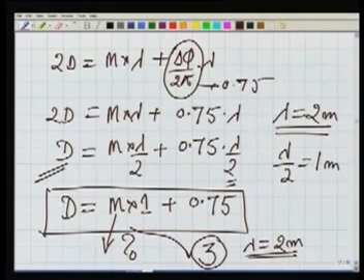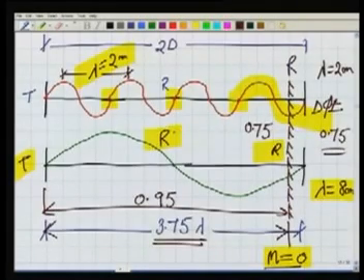Also another thing, because it may be confused that how we are selecting this value of 8 meter, how we are deciding that it should be 8 meter. 8 meter onwards, any wavelength that you select, the phase difference will increase monotonically. For any other wavelength which is less than that, the phase difference will sometime be less, sometime be more. So it will have a different kind of distribution. It will not increase monotonically. But here in this case, it will have a monotonic difference. Constant, either increasing all through.